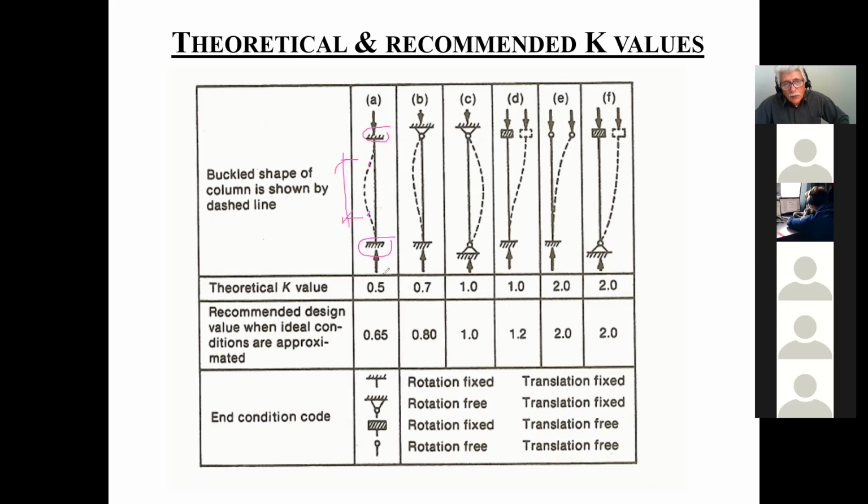In theory, and that's why we can actually reduce the length of the column to theoretically only half its length for buckling. Okay. The same thing happens here. Here it's fixed and it's pinned there. So if you look at the point of inflection somewhere around here, and then go all the way up, you're looking at 70% that will deform and possibly buckle.